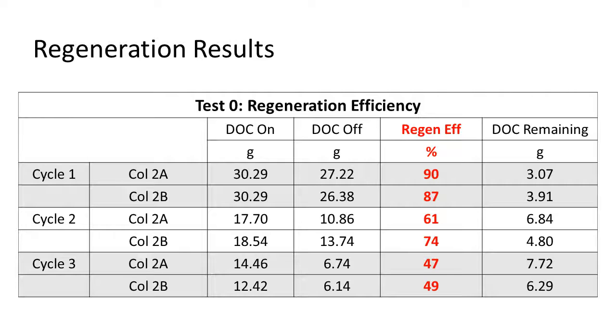So I'm open to comments or questions about that. Moving forward, we're going to be trying to compare these: here would be sodium chloride, here would be sodium bicarbonate. So there are 2 comparisons, right? There's the within-a-cycle comparison of chloride versus bicarbonate, and then there's the longer-term possible deterioration. Those are 2 separate issues that we can look at. Ideally, this shouldn't be declining to such a significant extent, but with the next test, we'll swap out the resin, and the iron levels are lower now, so I think this won't be as big of an issue.